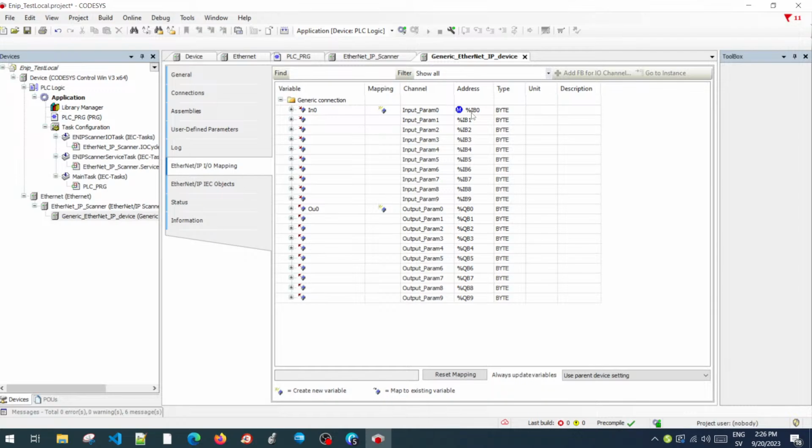Okay. Interesting. Yeah. So what happens, or why this is done like that, is because if we go back to Codesys, actually we could say that the memory coming from this slave could go to IB100 and so on. Right. And this is something that just the PLC knows. The slave never knows where these 10 inputs and outputs are located. Okay. So, and you can, as you see, it's totally okay if I do it like that. In Codesys. Okay. Yeah. So that's why.